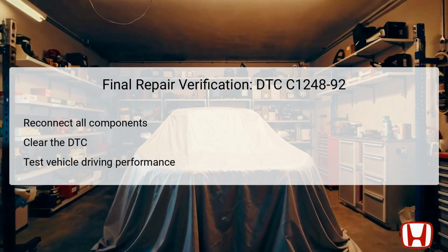Once all necessary repairs pertaining to DTC C1248-92 are completed, the final verification phase is critical to confirm successful repair. Begin by reconnecting all components, ensuring that all connectors click securely into place. Next, clear the DTC using a diagnostic tool to reset the vehicle's monitoring systems.